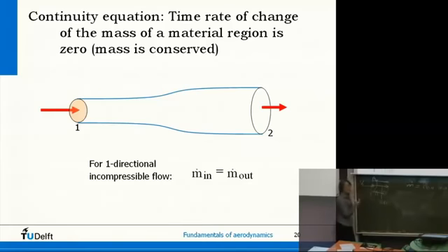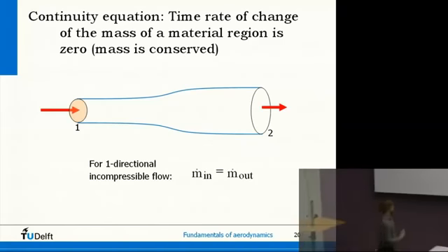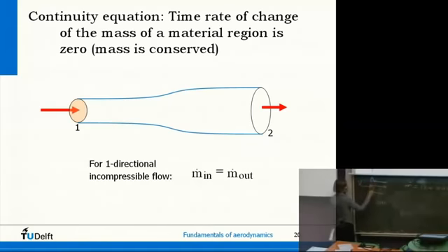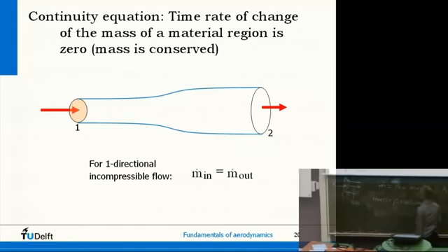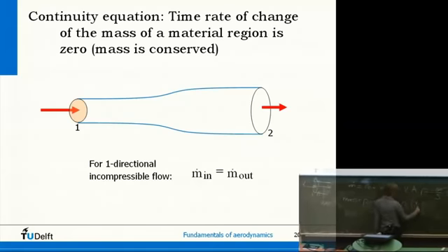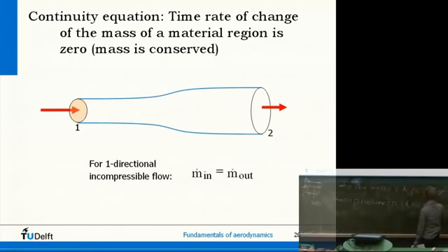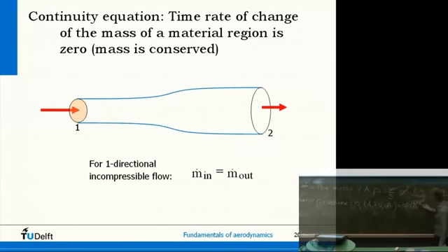So if we think about the mass that flows in, it's actually the mass inside this volume, right? That flows in a time dt. Well, the area on this side is A1, and the length there is v1 dt. So mass is density times volume. So rho 1, density, times volume, that's A1 times the length, v1 dt. So rho A v dt. That is the total mass.